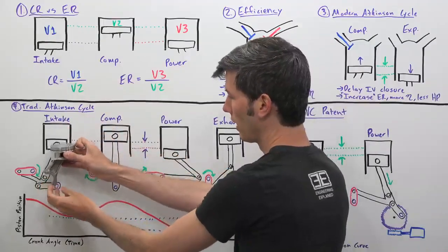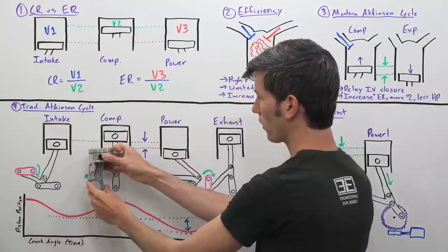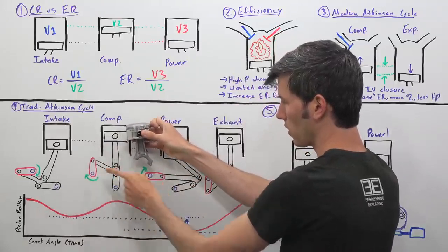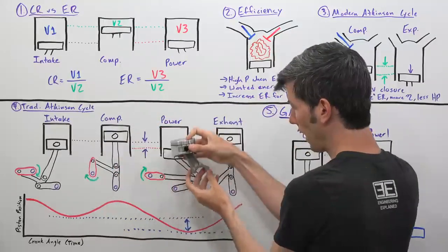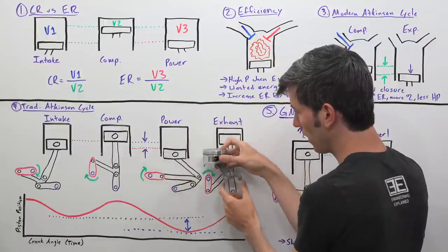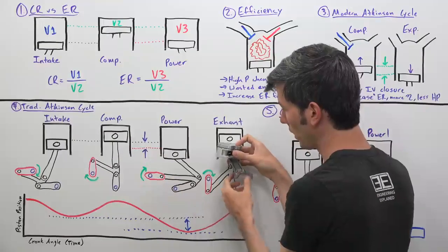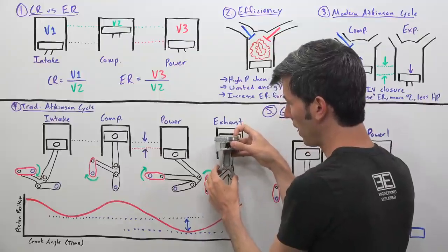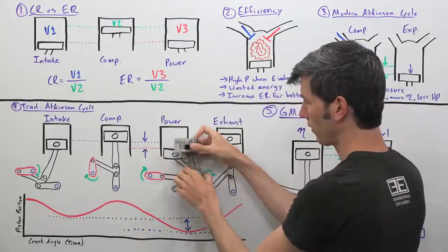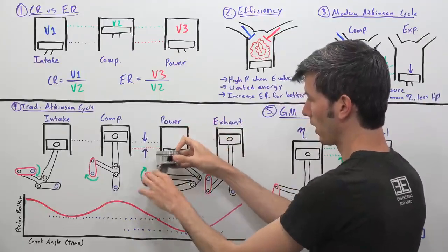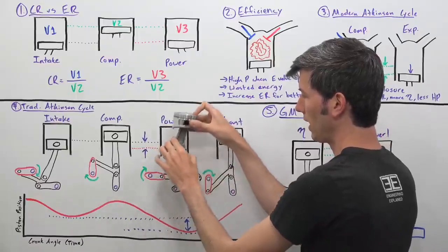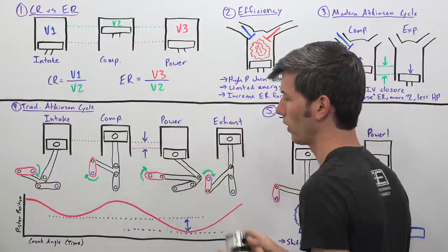And by going back and forth, it's pushing that piston up each time. So you can see here, it's going to rotate 90 degrees. It's going to start to push that piston up. Then you're going to have it continue to rotate another 90 degrees, your crankshaft. It comes back down as that connecting rod is now all the way on this side. Then it continues to rotate down. So as it rotates down, it pulls that center link over. That pushes this back up. And so you just repeat that with this piston going back and forth like so, up and down with the connecting rod going back and forth, rather than a circular motion like you see in a traditional Otto cycle engine.